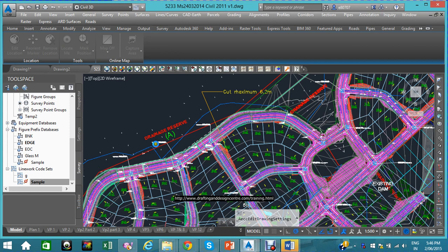So when we have a survey, before we import it, this is a very crucial step for engineers: liaise with the surveyor, inquire about the datum information and which zone information is being gathered, and put the survey onto the ground and map, aerial map or hybrid map, and then see how this looks.